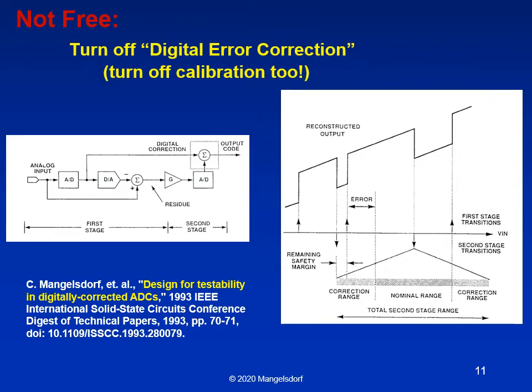Okay, here's another trick. Usually, modern A to D converters have some sort of calibration on them, and usually the designers put some mechanism for turning that on and off, so that you can diagnose how the converter is doing before the calibration and how it is doing afterwards, and whether there are any artifacts associated with either state. So that usually happens automatically.